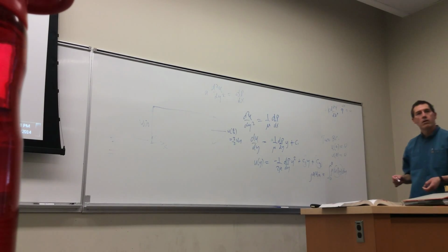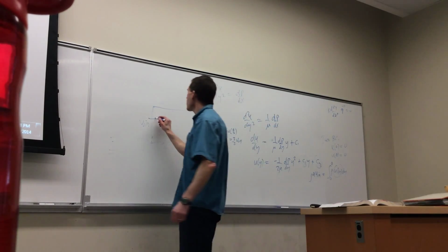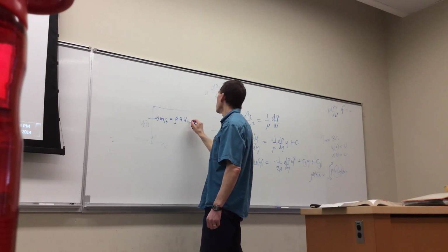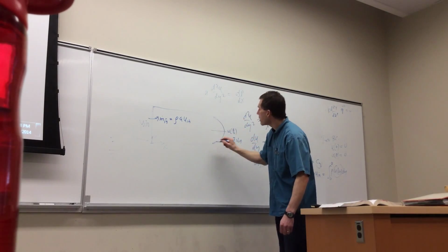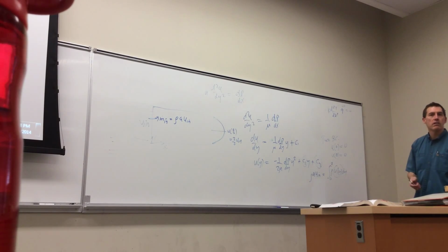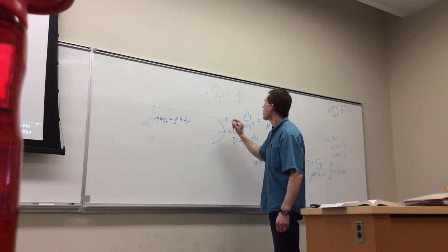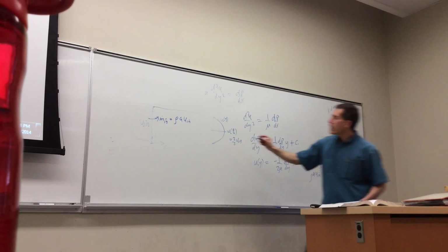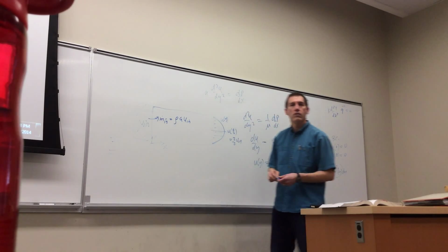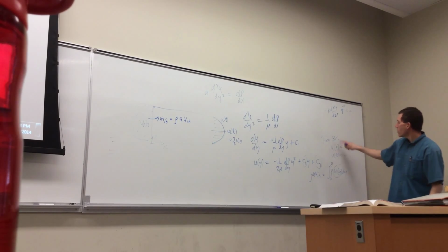Is that equation for the integral the continuity, you said? This is, okay, so the m dot in is equal to ρ times A times UN, right? And the m dot here is the integral from 0 to A of ρ times velocity dy. This is U(y) here. So you're saying this area here is equal to this area here. And it connects these coefficients that you got from using those boundary conditions.